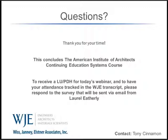The next question says, you mentioned that heat strengthened and tempered glass are stronger than annealed glass. What type of strength are we talking about? Tension, flexure? So as you saw in the presentation, what provides the strength is that residual compressive strength. When it comes out and gets quenched, it gets locked in a high state of compression, and that gives greater resistance to the thermal and mechanical stresses, but also gives you greater load resistance as well.